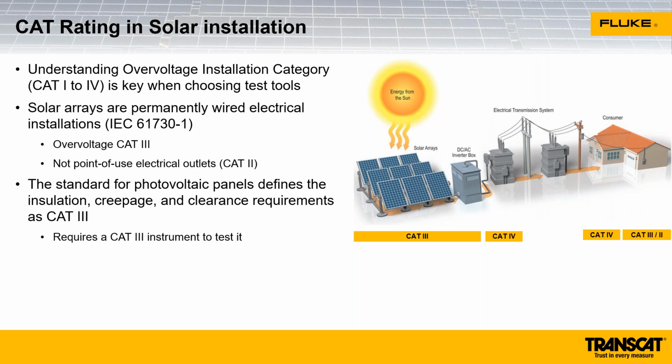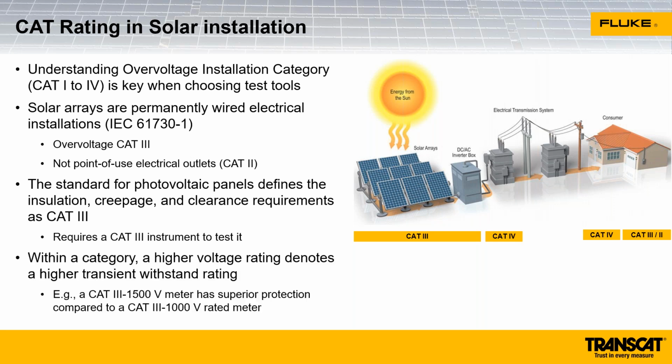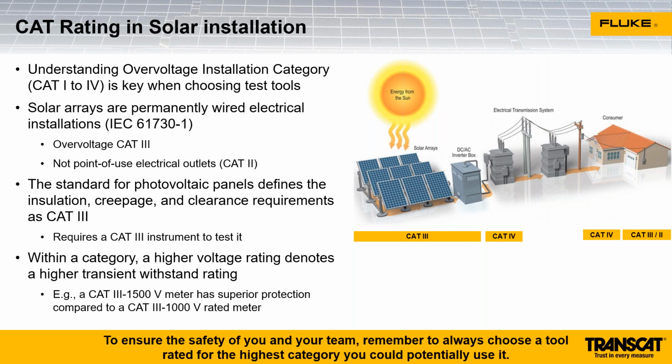So as we're looking at instruments and trying to decide what tool to get, we will need to know what category environment we're working in. And again, solar arrays are considered a category 3 environment. Within the categories, you also have voltage ratings, and we're going to talk about these more in a second. The bottom line is to know what type of environment you're going to be working in and choose a tool